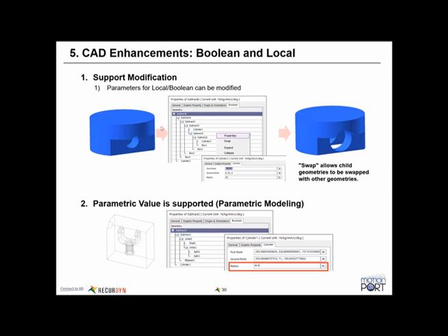Our capability is quite robust, so you can go ahead and add fillets and different things. I've had cases where there was contact going around the corner of some geometry, but the way it was modeled, the corner was perfectly sharp. When you have that kind of a 90-degree turn on a surface that's supposed to be a contact surface, numerically it is not well defined where you go past that corner. So putting in a fillet, so that you have this gradual change of angle, is a lot more reasonable, and the contact calculation works a lot better.